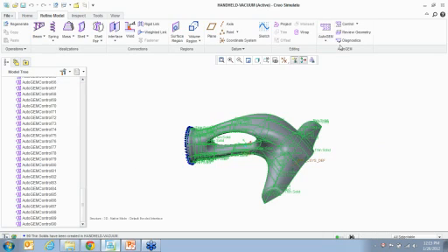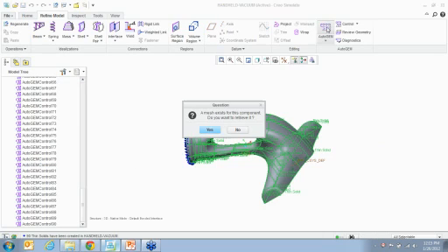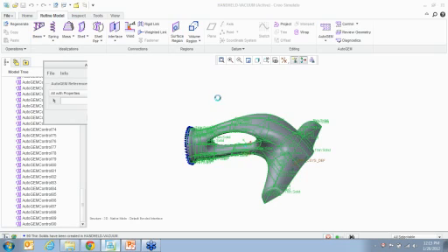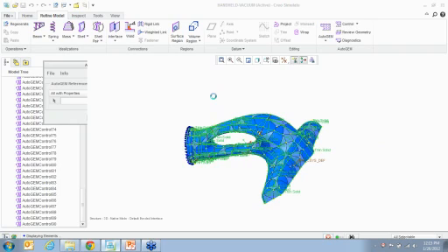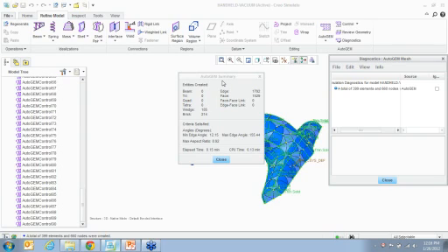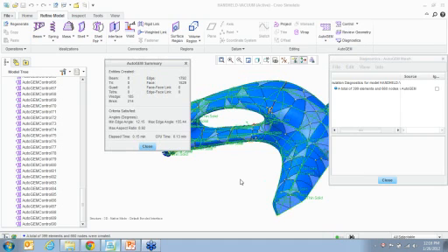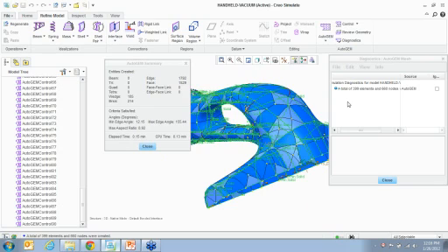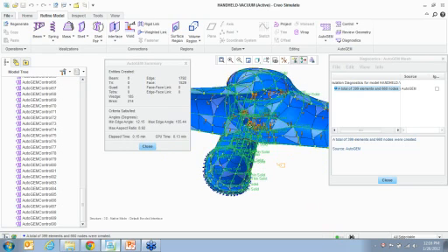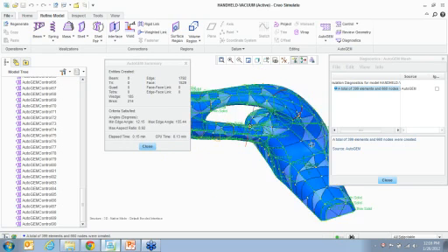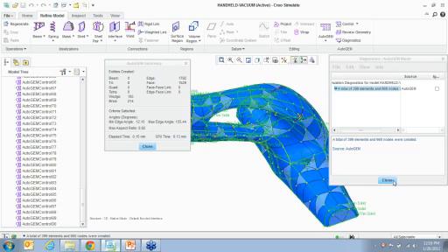Now if you go do an AutoGEM, you can see the number of elements would be in the 400 range, and the elements are much bigger and thinner, and very few compared to what we had earlier. You can see it's 399 elements instead of 10,000 elements. All right? So this really helps to speed up the process.